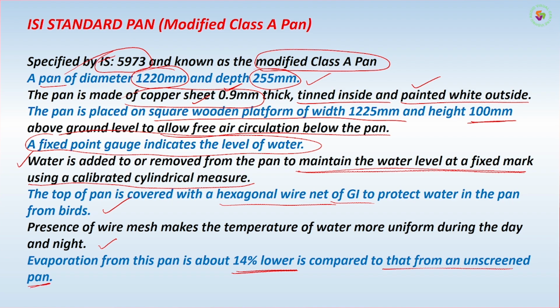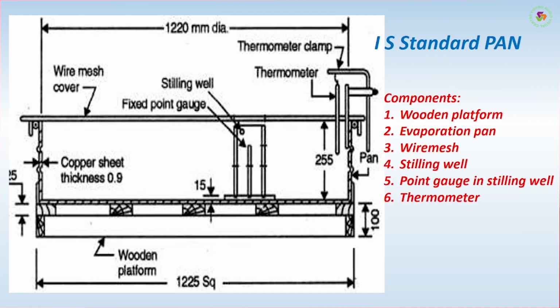So evaporation, whatever you get, basically the evaporation is multiplied by the pan coefficient, that we will multiply. Naturally, because this metal is a smaller thing, evaporation will be more, so we need to multiply it by 0.7. So 0.7 or 0.8 depending upon the type of the pan, so to get the complete evaporation.